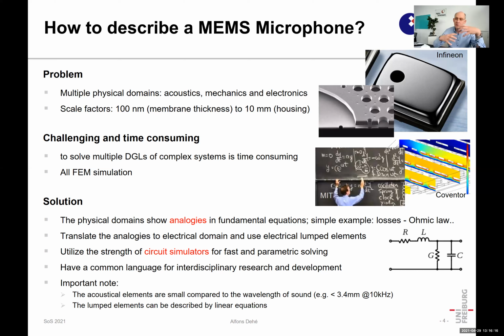And if you translate your acoustic or mechanical acoustical device into this formulation, you can use quite major circuit simulators that are fast in solving complex equations or networks. And then it's very easy to parameterize devices and geometries under consideration. So it's major, and yes, it is possible.